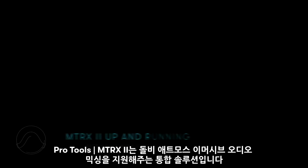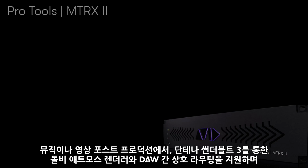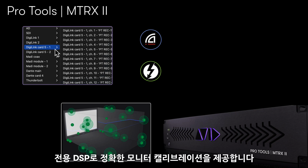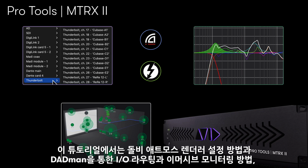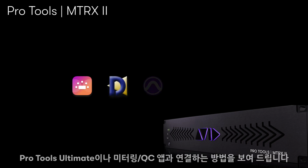Pro Tools Matrix II provides a comprehensive solution for working with immersive audio for Dolby Atmos, whether working with music or post-production, from routing to and from the Dolby renderer via Dante or Thunderbolt 3, to providing precision-calibrated monitoring with dedicated DSP for tuning and bass management. For this tutorial, we'll examine configuring the Dolby Atmos renderer, leveraging DADMAN for I/O routing and immersive monitoring, connecting Pro Tools Ultimate, plus additional software applications for metering and QC.